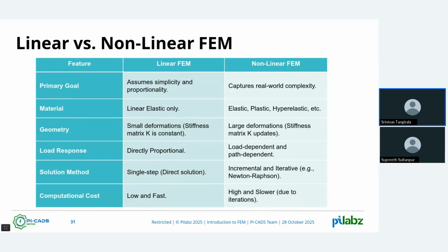Yeah, we briefly talked about linear and non-linear. For example, in deformation, there is also an elastic region and a plastic region, right? If your deformations are in the plastic region, linear FEM doesn't work. You have to go with non-linear FEM. For geometry with small deformations, linear is fine. For large deformation, we need non-linear FEM.